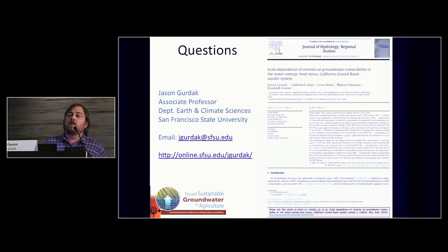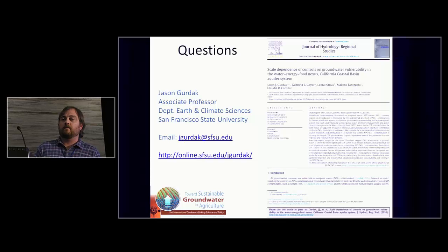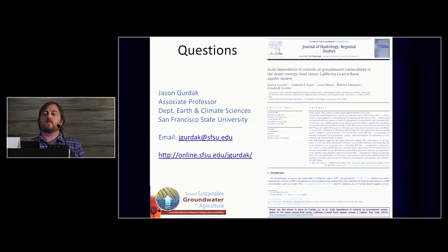I was wondering, are you suggesting to measure the dissolved oxygen concentrations directly in the field using a sensor, because it may change over time? And maybe a second one, you may also have other components like iron, and also say something about the redox conditions of the sample.